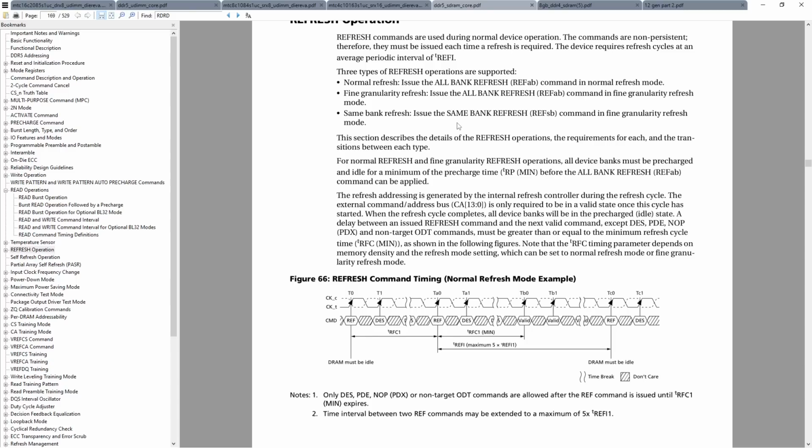This is not a problem when storing zeros because zero is literally a low voltage, so the capacitor naturally is going to sit at a low voltage. Ones are a bit of a problem because the tiny little capacitors making up your memory stick leak charge over time. So if you charge them up to write a 1 and you let them sit there, eventually they will revert back to being a 0.